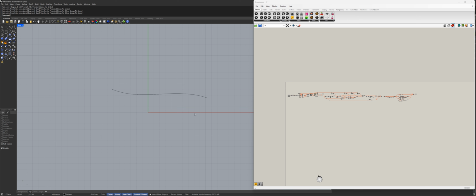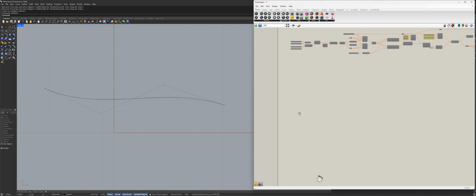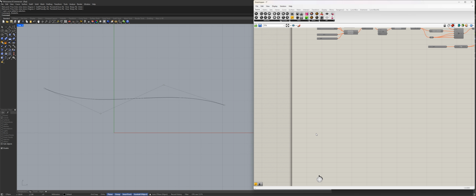Now I would like to visualize the control points. So I click on the curve and type F10, which is the default hotkey. So my control points are visible for the curve, even though the curve is deselected. Okay, let's zoom in a little bit and inspect our curve. There are very specific instruments to inspect your geometry, and every CAD system has a bunch of its own. Rhino of course has its own, and we will inspect it.